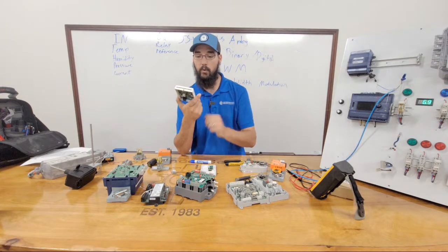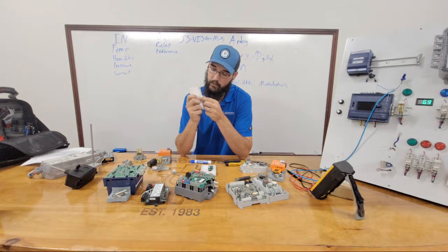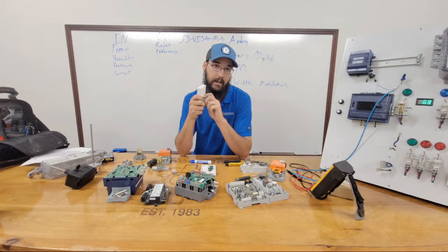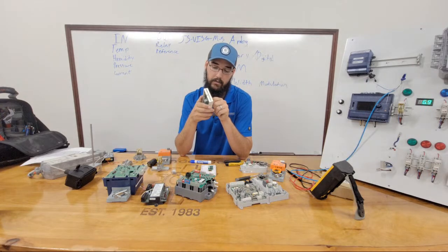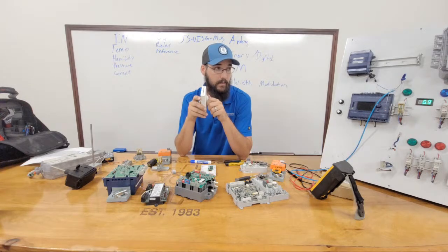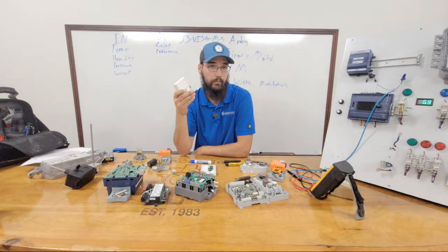request, right? So they can adjust this on the program to where dead center would be 0, and you can have, say, minus 2 degrees or positive 2 degrees. So if set point was 70 degrees and they had a 2 degree plus-minus span, then the tenant could adjust that from 68 to 72. And dead center would be their 70 degree set point.